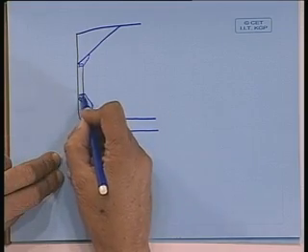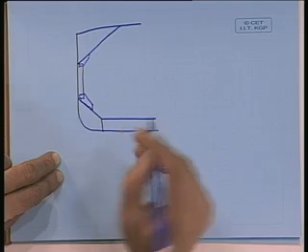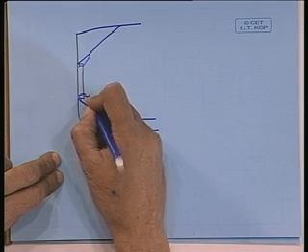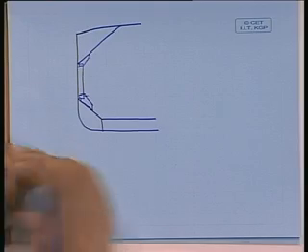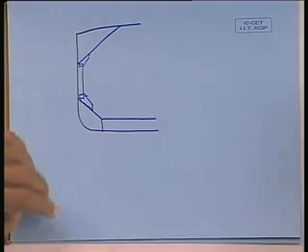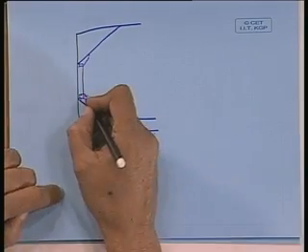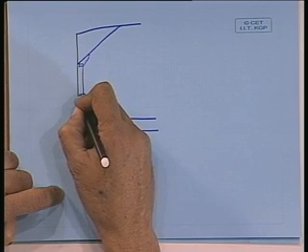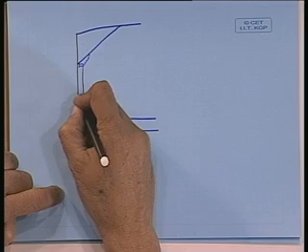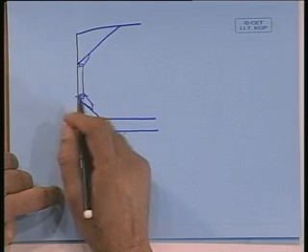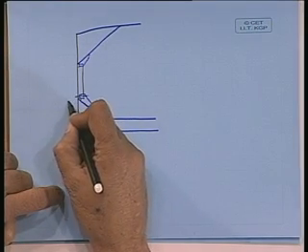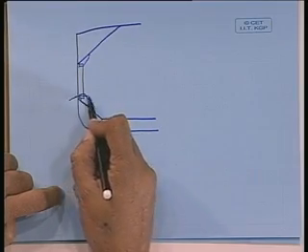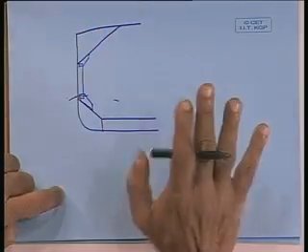Okay. Now the majority of the vessels, they found that the crack started from here, and this crack and the bracket which started progressively propagated to the stiffener here, and then finally to the hull, and opening it to the sea, and therefore from this side the water entered and slowly it flooded this part.